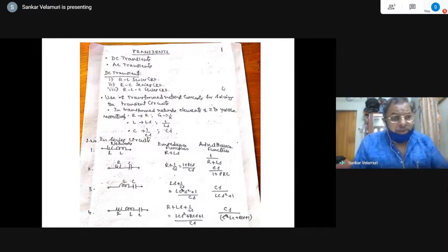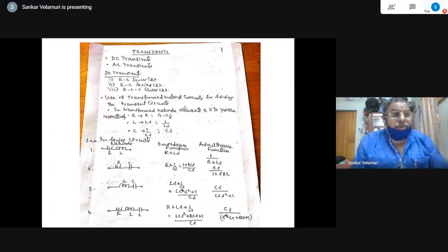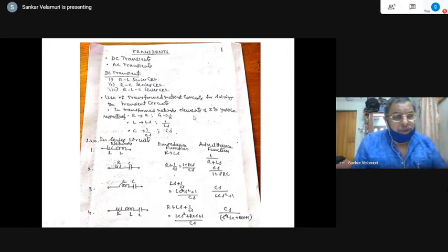And this is the concept, I hope you are aware, in transform network parameters also. Instead of open circuit impedance parameters, that is Z11, you can say Z11 of S, that is transform parameters, because you want to analyze the frequency spectrum of the corresponding parameters, you have to necessarily use this. So there are two types of solutions, time domain solution and frequency domain solution.